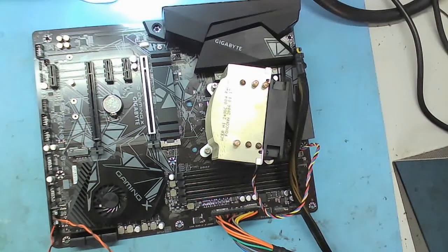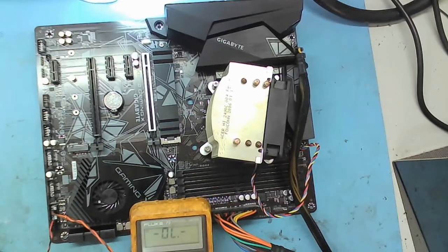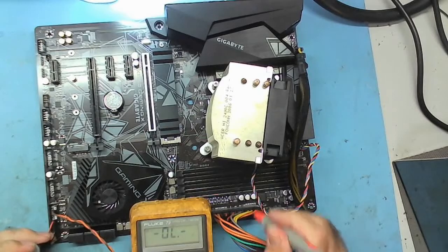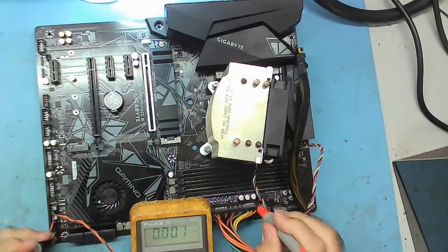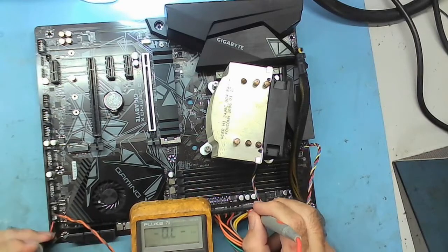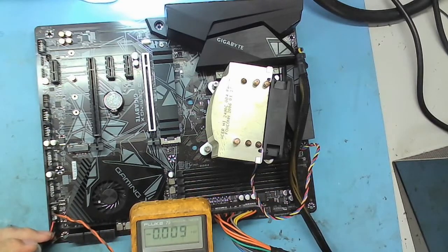Turn the power supply on. Let's have a look to see if we've got any 5 volt standby on this. That'd be interesting. So power from here should be standby now. Oh, voltage range. Standby, yeah, 5 volts. 3.3 volts on the switch. Should be good.